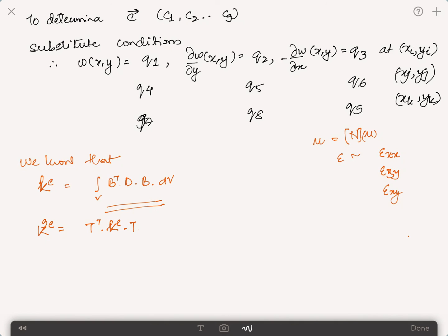And in this case, actually, it's quite opposite to what we did with the beam. In this case, it will be very clear that your transformation for the out of plane direction doesn't have to be done, because the out of plane direction is Z, which is the thickness direction, and the rotations are actually along the directions X and Y, which will need to be transformed.